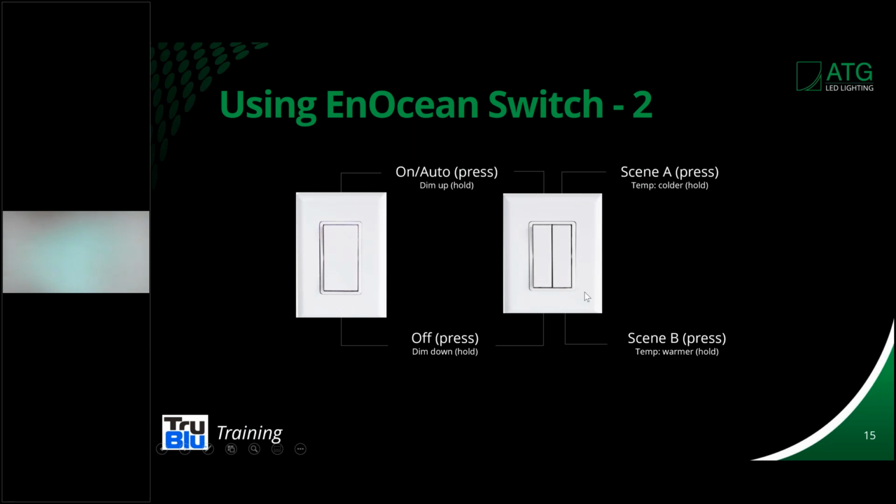Now, when we have color tuning fixtures available, these buttons will also be able to address the color tuning. So if you hold it to the top, it will get a cooler light level. If you touch the bottom and hold it, it will get warmer. So there's a lot of capability here just with the switch itself.